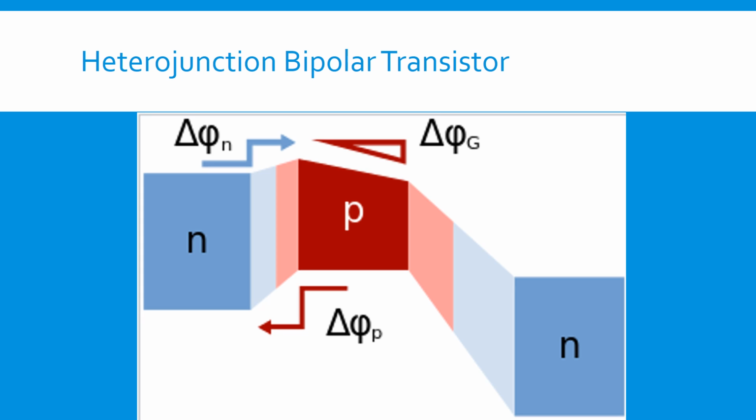The heterojunction bipolar transistor is an improvement of the bipolar junction transistor that can handle signals of very high frequencies, up to several hundred gigahertz. It's common in modern ultra-fast circuits, mostly radio frequency systems. Heterojunction transistors have different semiconductors for the elements of the transistor. Usually, the emitter is composed of a larger band gap material than the base.